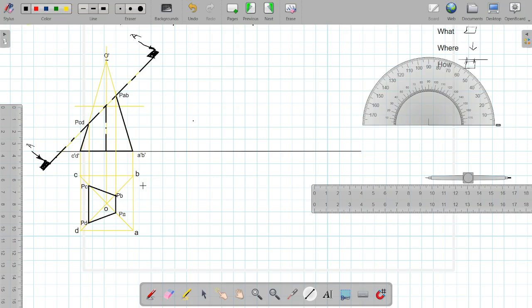Now we have to join the remaining part. So again it is simple. What is remaining here? Just observe the front view. We are remaining with PC to C. This line is visible from PC to C. Similarly, from PD to D. So I will join this PC to C. I will make it dark, which we have not done earlier. Now it is visible, so it will be made dark. Similarly, from PD to D.